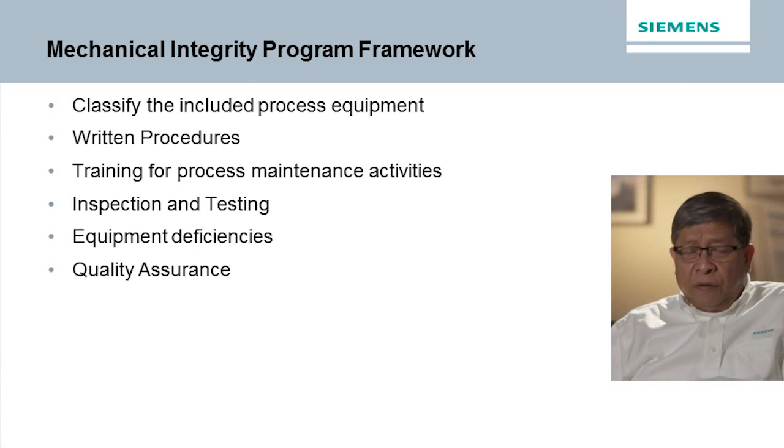And J6 of the mechanical integrity law talks about quality assurance. So when we build a vessel, there has to be all this process safety information from the design and the calculations and quality controls, testing, NDEs, and all of that. So most of us do a good job with new fabrication.